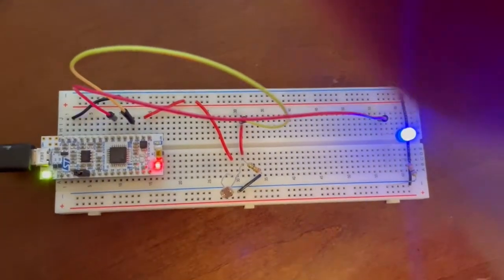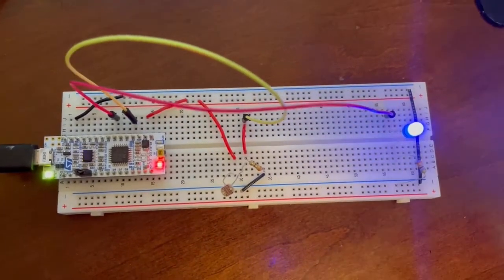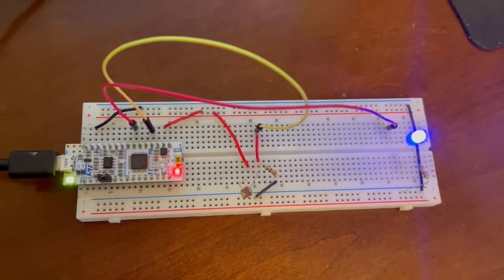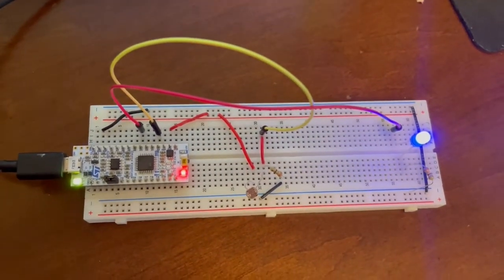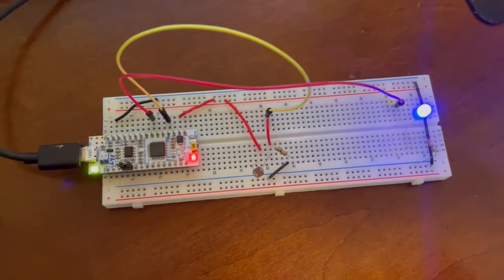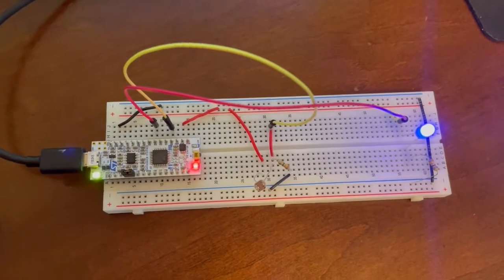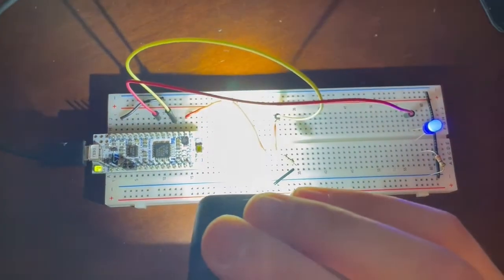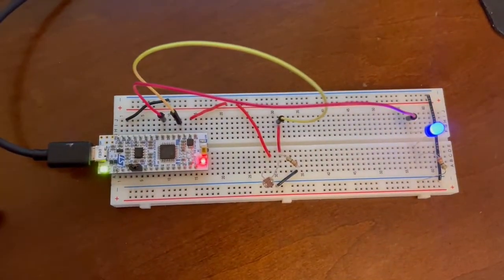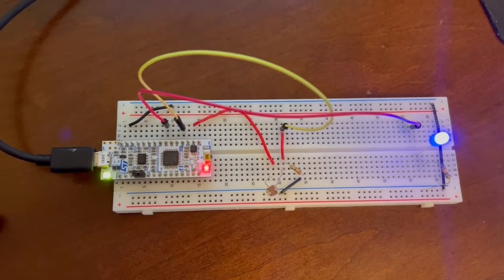So essentially what we should expect is this LED is on currently, which means the environment is not bright enough to reach the optimal range. When I shine my flashlight on it to increase the brightness of the environment, the LED is going to turn off in an attempt to reduce the brightness to get it back to the 600 to 1000 lux range. As you can see, the LED is turning off, and when I remove the flashlight, the lighting is back to not being bright enough, and so the LED again lights up.